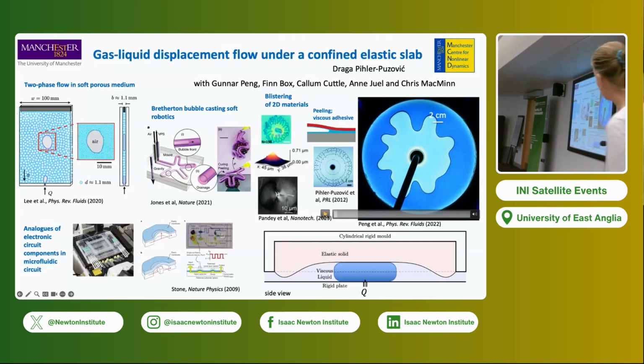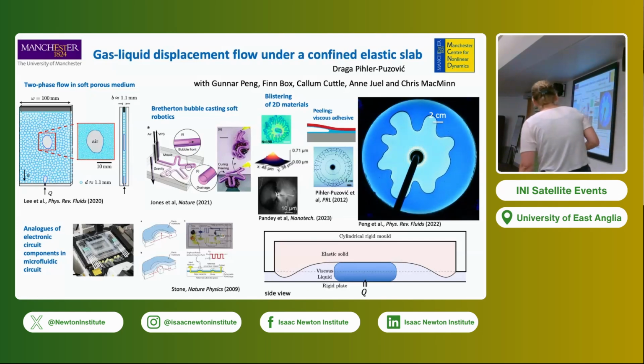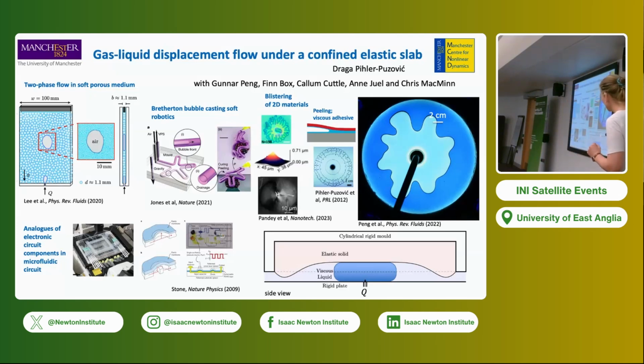At the edge of the cell, you basically start forming this white circle, which means that you have basically no liquid left at that edge. The reason why this circle is formed is because as you were injecting your liquids, you also deformed your elastic slab. You deformed it in such a way as to bulge it near where it's constrained at the edges, and that bulge grew until it touched the opposite rigid wall and shut down the flow. Okay, so that's a phenomenon I want to understand, and in particular in the context of multiphase flow inside the cell.